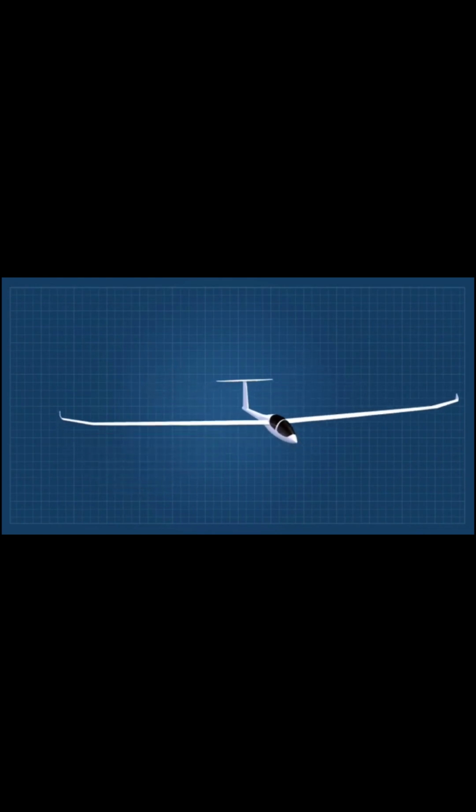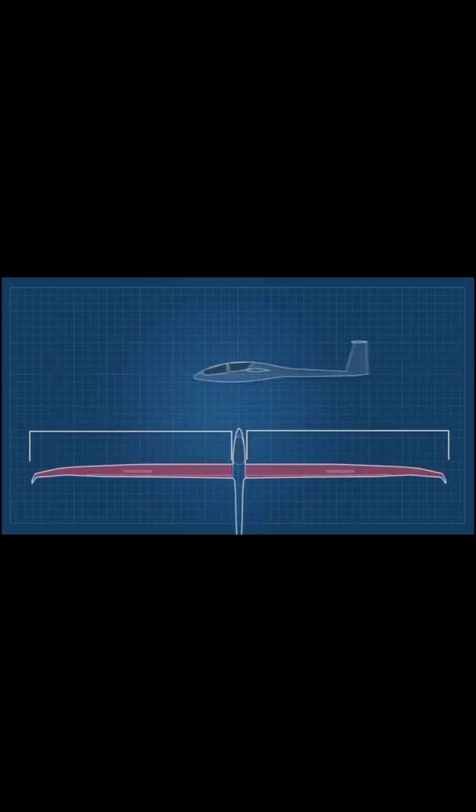The wings are also measured by aspect ratio. Glider wings have a high aspect ratio, and war airplane wings have a low aspect ratio. War or aerobatic aircraft wings generate more induced drag than the thin wings of gliders, but because they are short wings, they are more maneuverable. Maneuverability is a priority in warplanes rather than fuel efficiency. In the case of gliders, it is not necessary to make quick maneuvers, so the priority is given to efficiency, sacrificing maneuverability. That's why the wings end up being naturally long, because a large wing area is required with the restriction of a reduced chord wing to minimize the drag.